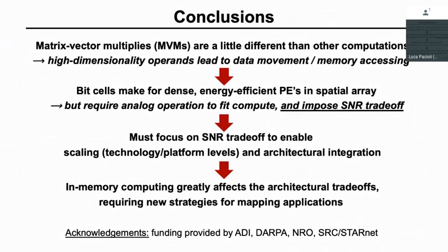So what you can do is you can do your accumulation. Essentially that ADC is converting the accumulated result. Maybe the requirement for the full dynamic range here was a 32-bit accumulator. What you can do is instead do an 8-bit accumulator or a 6-bit accumulator. I would argue that that is a more fair comparison.